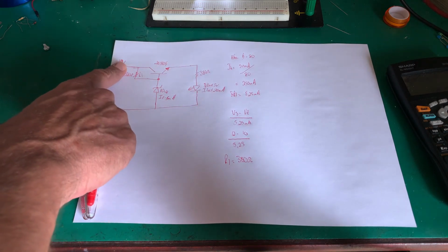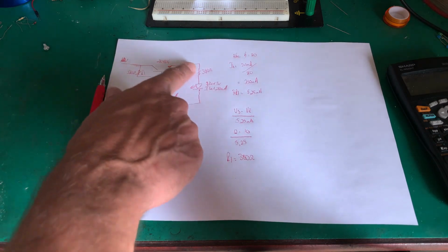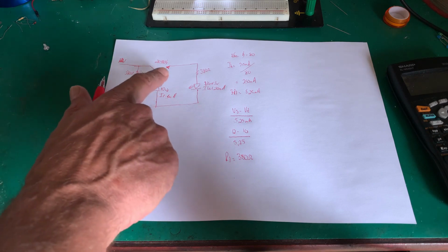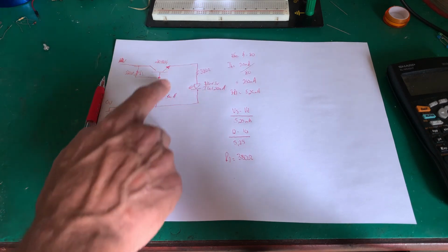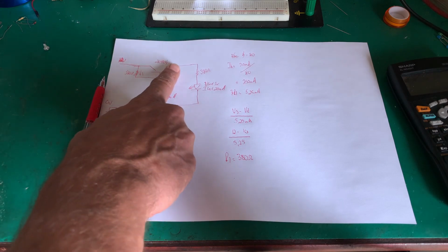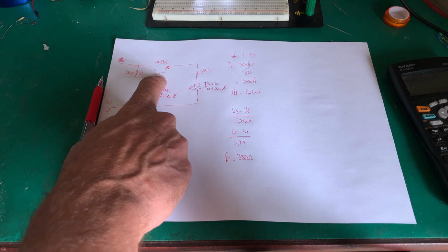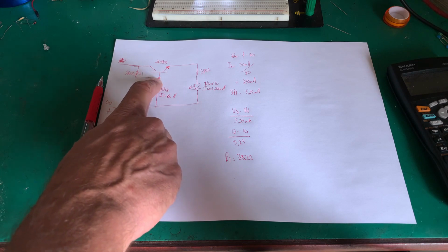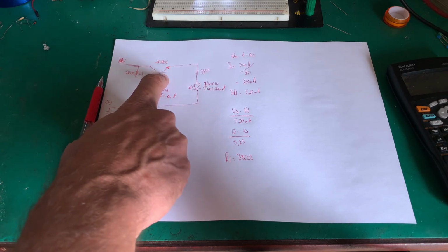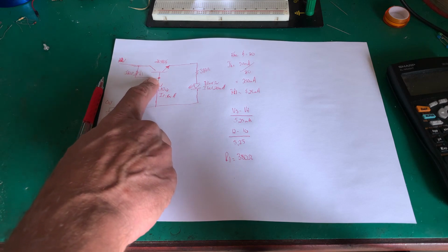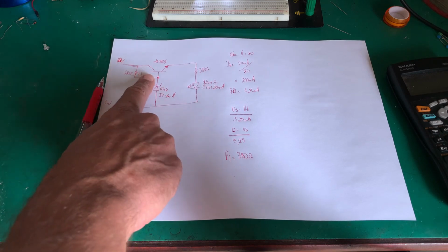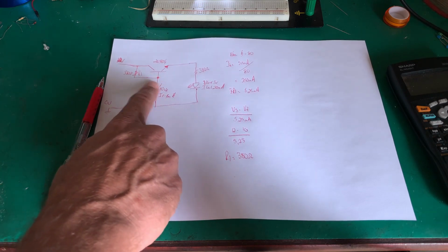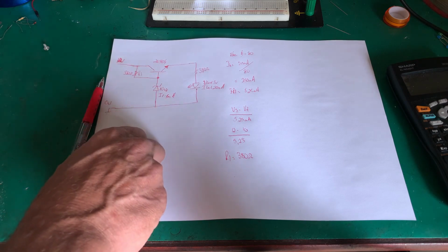What happens when the voltage goes too much? Because now we're trying to control the voltage here at our Zener voltage, which is 10 volts. If the voltage goes above 10 volts here, the base emitter voltage will grow, causing this transistor to switch off a bit, because now that gap has become less than what we need to actually conduct. The excess, obviously, because the input voltage would be rising as well, will start to conduct through the Zener. The Zener will strive to keep that voltage there at 10 volts.